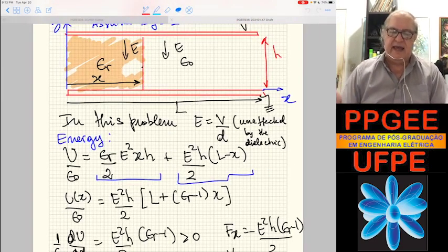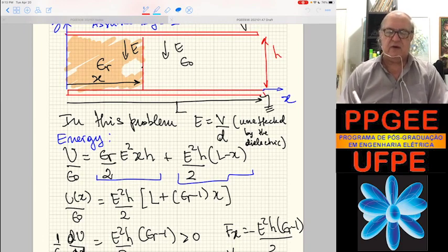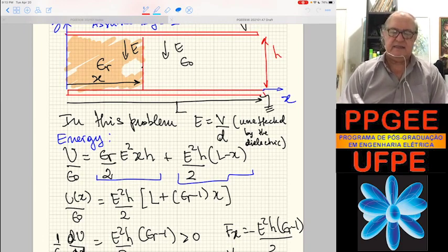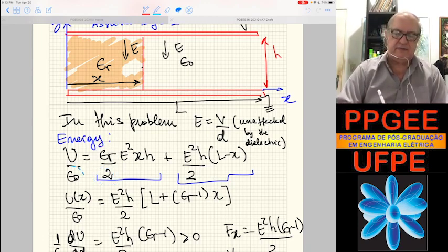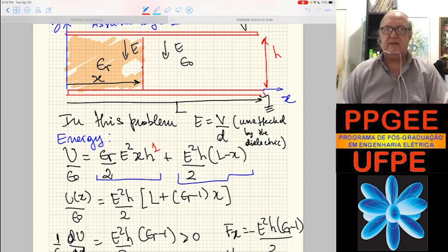So calculating the energy, I'll leave for you to calculate. This is the volume integral already, right? Factor of 2 here. Relative permittivity, I put epsilon 0 here. So I have the square of the field. Then X is the length of the dielectric, H is the height, which gives the volume, and times 1, I didn't put here because it's the depth to the plane of the page.